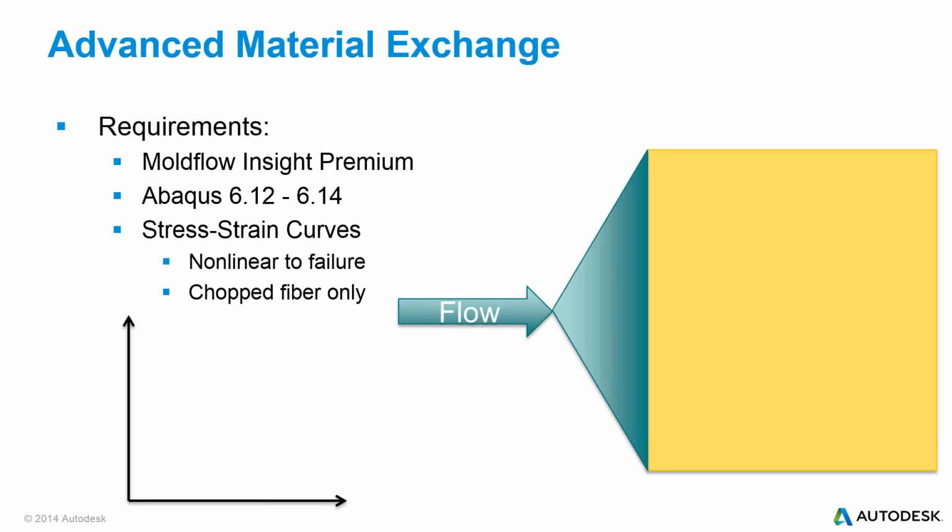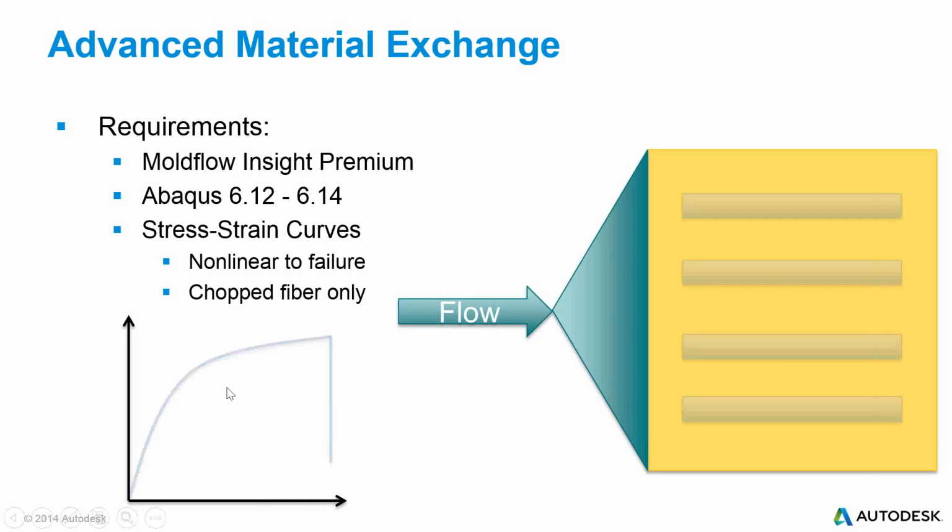When you want to run a nonlinear analysis using advanced material exchange, you need inputs besides those linear inputs that come from mold flow. So we also require that you input two stress strain curves that are nonlinear to failure. One is aligned with the flow.